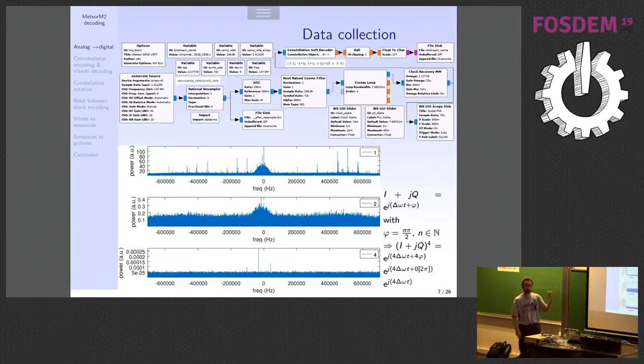So already I needed to learn a first word when I was doing this. I didn't know what a soft bit is. A soft bit is an IQ coefficient where your 1 and 0 are not yet saturated, but are still represented here by an 8-bit value, and you still need to identify whether it is most probably a 1 or a 0.